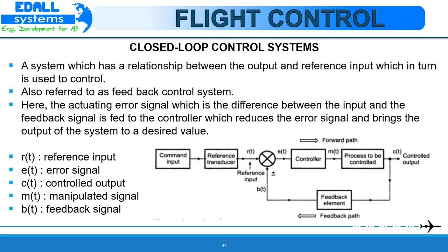Apart from this, there are a few disadvantages also: such systems are complicated and time consuming from a design point of view, and also costlier. Due to the feedback, the system tries to correct the error from time to time. The tendency to overcorrect the error may cause oscillations without bound in the system. Hence, the system has to be designed taking into consideration problems of instability due to the feedback signal. The stability problems are severe and must be taken care of while designing the system.